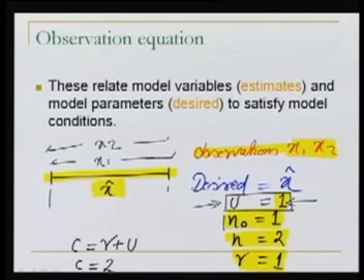Now here in this case, the total number of observation equations that we can write is equal to C. C means R plus U. Over here in this example, C is equal to 2, because we are including the model parameters also into the computation process in our least square solution or in writing these observation equations. So we will need to write C number of observation equations. Now how do we do it, particularly now in this example?